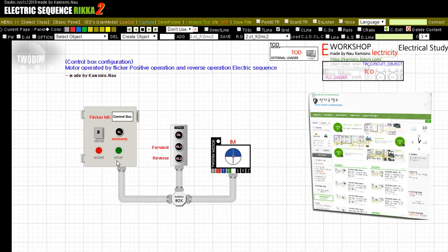The screen has an electric control box that we can easily see, and the control box has an electric wiring breaker and a lamp that operates on an overcurrent relay trip. You can also view each start button and stop button. The operation configuration is held for 5 seconds by the internal timer when the start button is pressed. After 5 seconds, the motor starts forward for 10 seconds.